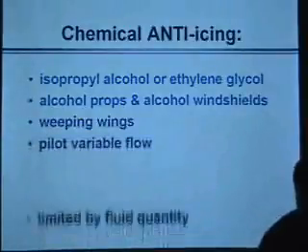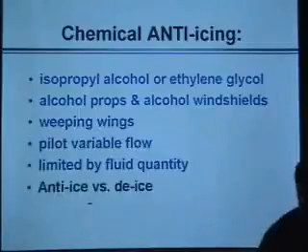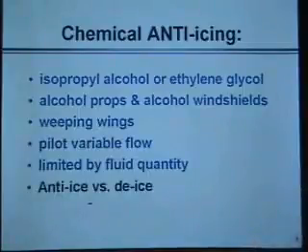So before you think you're in icing conditions, you're going to turn this on low, and when you get into icing conditions, you're going to turn it on high. Again, with limited fluid, you're going to want to get out of your icing conditions as soon as possible. In either case, whether it's alcohol props, alcohol windshields, or weeping wings, it only works as an anti-icing system, not as a de-icing system.